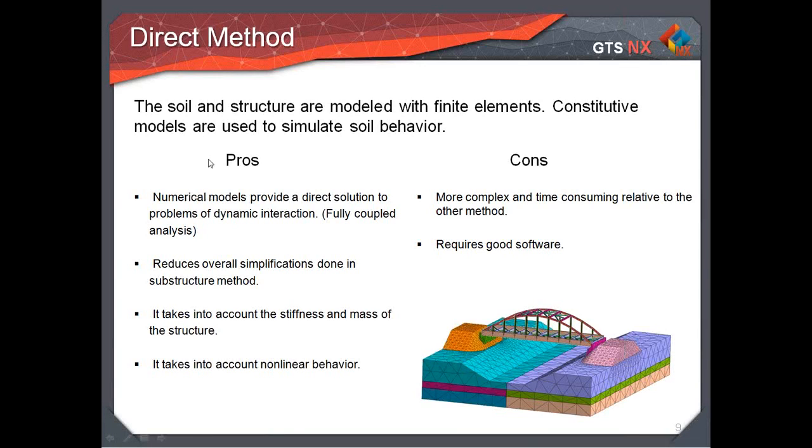So the benefit of this is that you can get a direct solution of your problem. It's a fully coupled analysis, and it takes away a lot of the simplifications that you make with the other method. You can even take into account the stiffness or the mass of the structure. However, as we mentioned, it's a more complex and time-consuming method relative to just applying some soil springs to your piles and running it from the structural point of view.